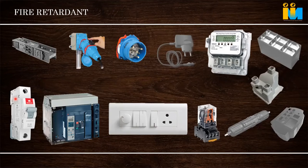So they'll put a lot of air vents, and periodical maintenance is done. How maintenance is done: the mold will be made of complete insert construction, with many small inserts, the more the better. In that way the mold will be made. Moreover, after one shot or so, the mold will be taken down, they will have a spare mold, and this will be cleaned by ultrasonic cleaning.